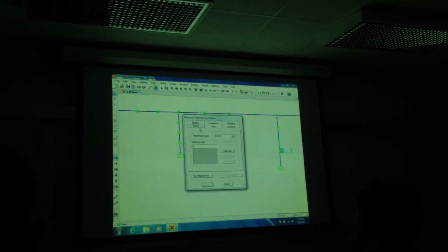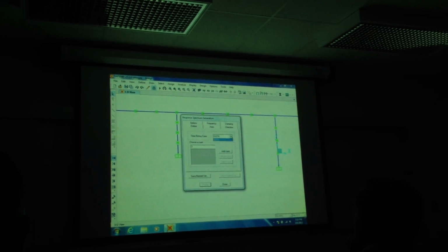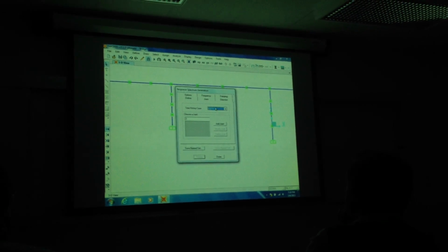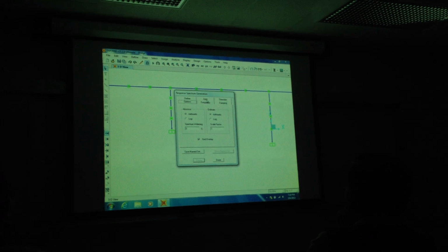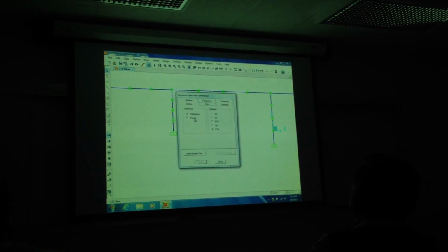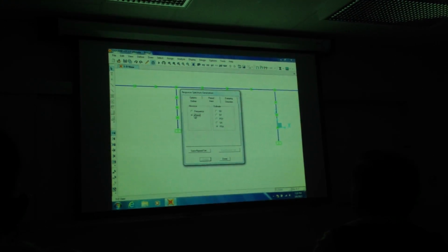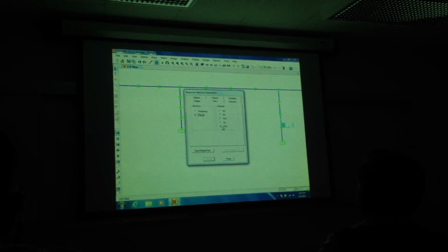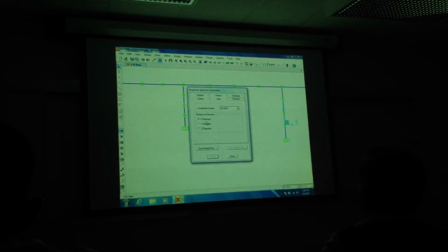Then define. It's telling you this is the earthquake time history, it's the only one in there, but if we ran different earthquake motions, you could pick different earthquakes or different loading. So this is fine. Axes: the horizontal axis, do you want frequency or period? I want the natural period of the structure versus spectral acceleration in the vertical. Direction, I want it in the x direction. That's the longitudinal direction in our model.